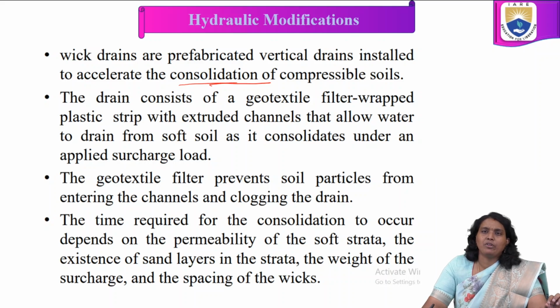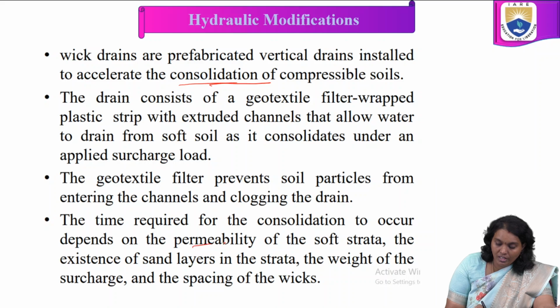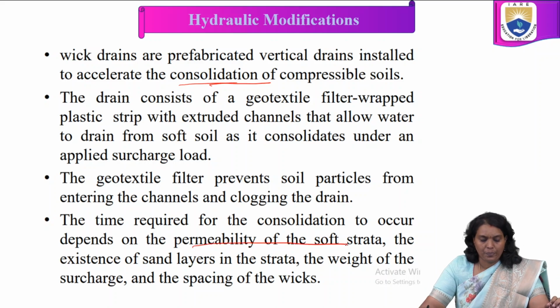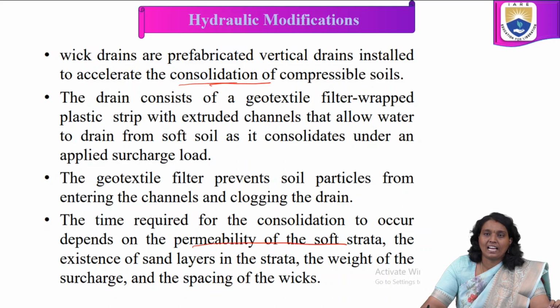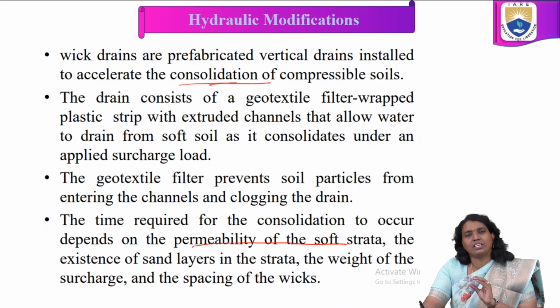The time required for consolidation to occur depends on the permeability of the soft strata and the existence of sand layers in the strata. The weight of the surcharge and the spacing of the wicks depend upon the permeability, how many soil layers there are, how they react, and the effective weight of the soil.